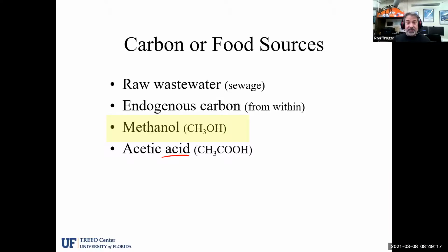And anytime you're dealing with an acid, you also have to have proper PPE and make sure you're handling this chemical appropriately. We definitely don't want to treat acids with disrespect, but acetic acid is another common chemical used, sometimes known as acetate, and sometimes fed into the wastewater to supplement the carbon source. Coming down the list, we see this crazy thing. It says dog food. Why would we feed dog food to the wastewater plant?